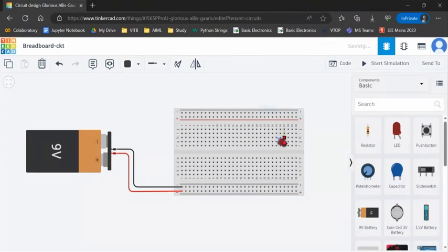So we should be rotating it further. We should be connecting such that each terminal is connected with two different vertical lines. So this will be the vertical line for the anode, and this will be for the cathode. Or we can place it here, anywhere between any two vertical lines. Or we can put it in the 19 and 20 columns. So the 20th vertical line will be indicating the anode pin, and the 19 will be indicating the cathode. Okay, so this is one thing.